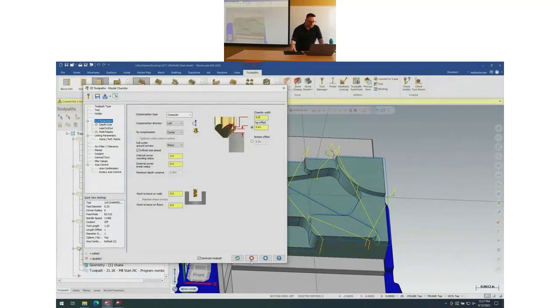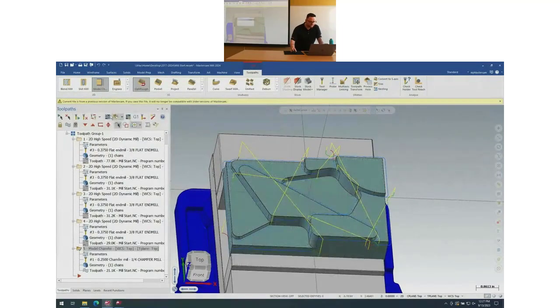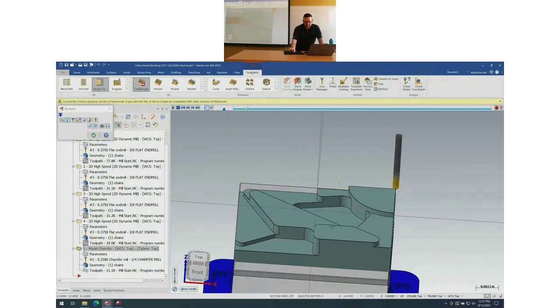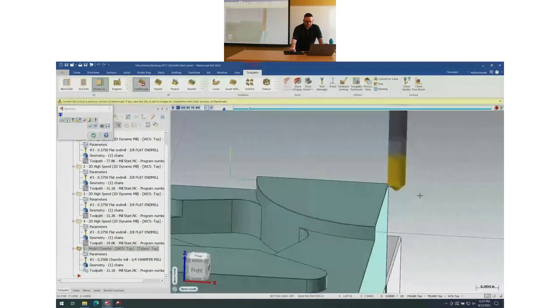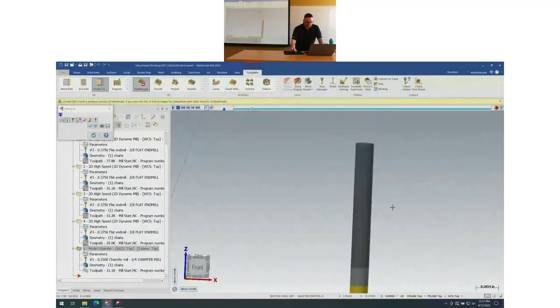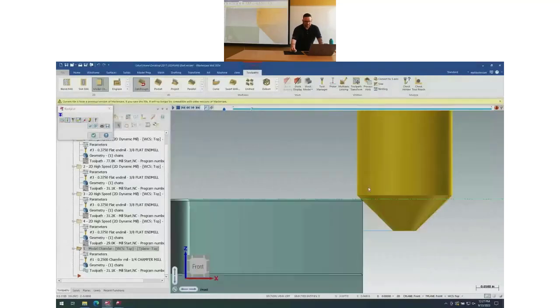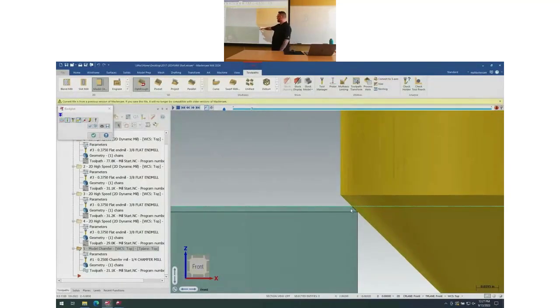I did not mean to click verify. Okay. So, and we'll turn off the quick verify for this. I miss my 3D controller. Although this view cube's really neat. Okay, so you can kind of see the way that this sits now, right? It's going to sit right along that chamfer because it knows the definition of the tool and the definition of that chamfer. And when you're doing it this way, you pick that top edge and it will compensate that way.